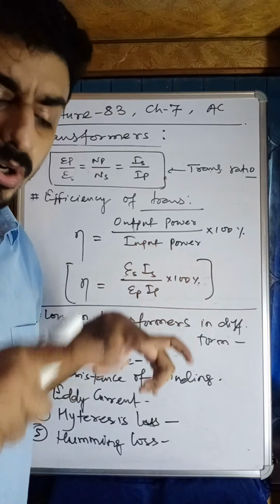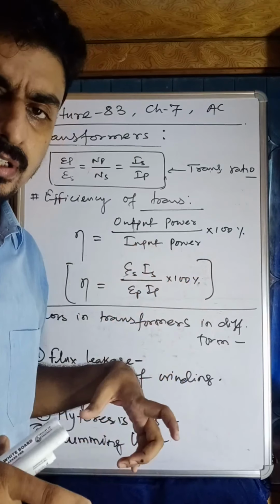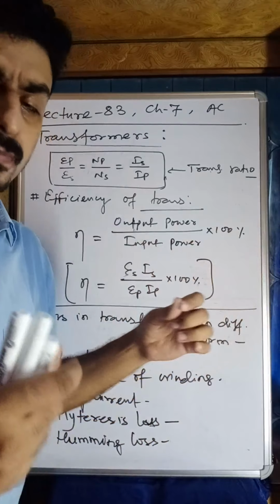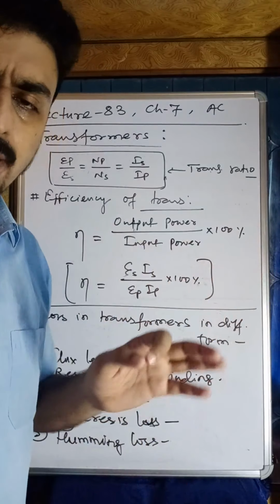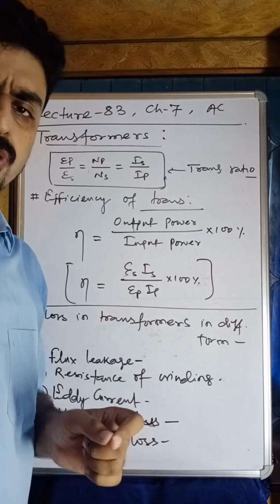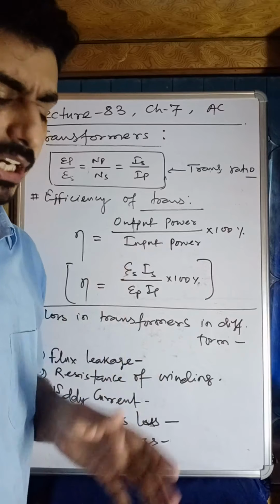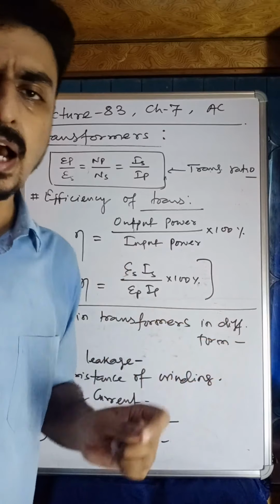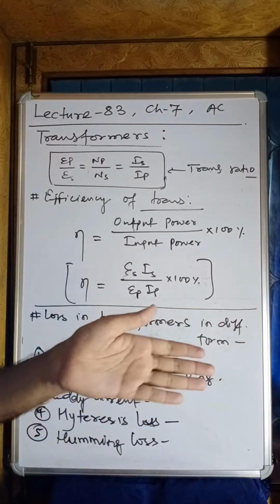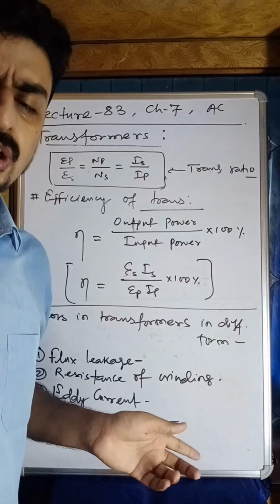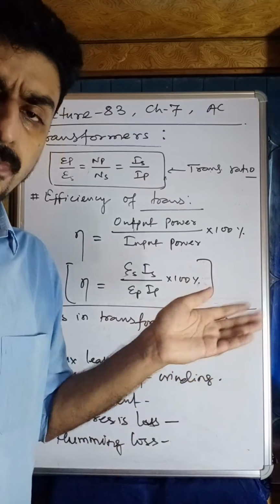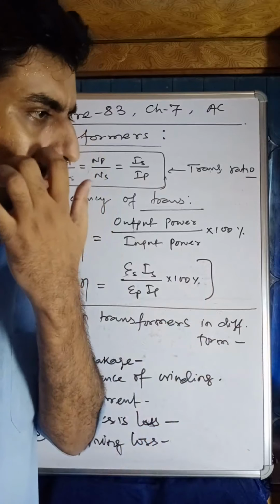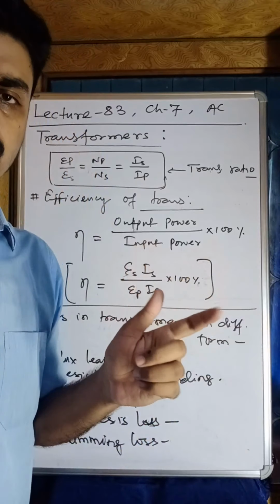if the winding or stapling of the coil is not very perfect, or after some time it becomes loose, then the AC current having some frequency, that frequency energy starts oscillating the iron core. If that iron core oscillates due to the frequency and the oscillation matches with the frequency of AC, they produce sound due to the resonance.